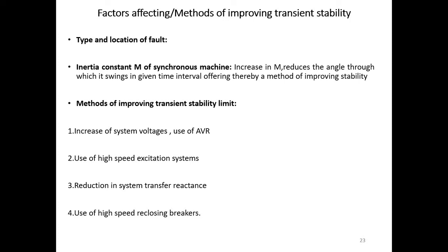So whenever a fault takes place on a system, the voltage at all the buses is reduced. At a generator terminal, this is sensed by the automatic voltage regulator, which helps restore the generator terminal voltage by acting within the excitation system. Modern exciter systems having solid state control quickly respond to the bus voltage reduction and can achieve one and one half cycle gain in critical clearing time for a three-phase fault on the HT bus of the generator transformer.